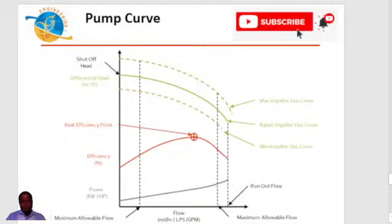Now, it's also very important if you look at the efficiency curve. This is also on the pump curve. You will also have an efficiency curve. Don't forget, I mentioned that it is not ideal to run a centrifugal pump at these two extremes of zero flow or the run-out flow. Now, look at the shape of the efficiency curve. On the efficiency curve, you will see a point like this, denoted as the best efficiency point.